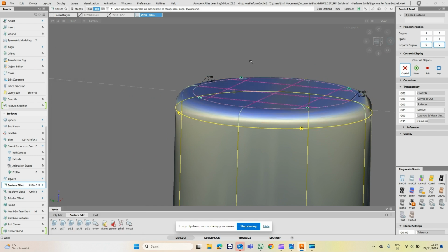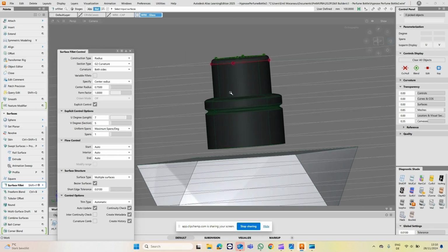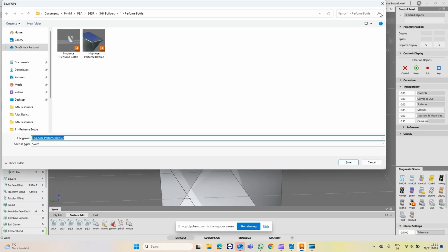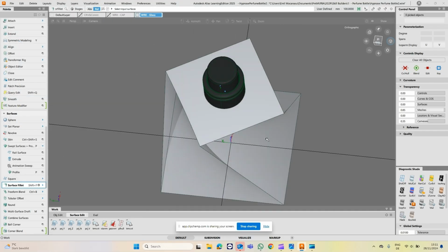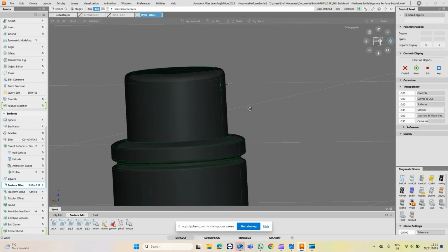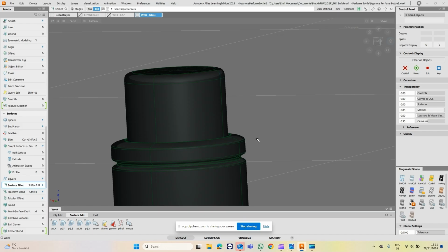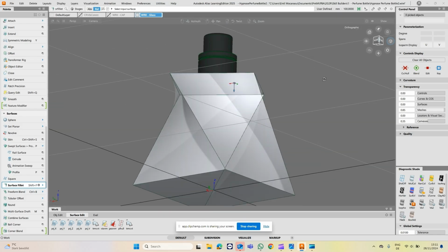All off. Switch to Viz 1. That's shaded correctly. That's done. Now we can save up. I recommend saving before using the fillet tool because it has a nasty habit of biting you. Now that volume is done.